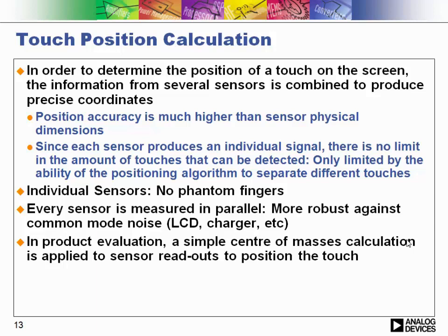So what you do is combine inputs from many sensors and do a kind of curve fitting. Obviously, the sensors that are farther away from your finger have less capacitance, and the one you're closest to has higher capacitance. Then you just look for the peak. That's the finger. There may be many algorithms to find your peak.